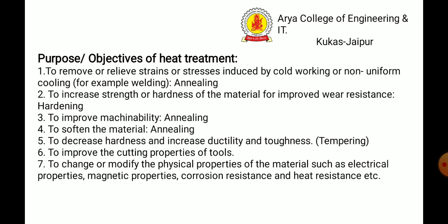The main purposes and objectives of heat treatment are, as we said earlier, to improve mechanical properties like machinability, to soften the material, to decrease hardness, to increase ductility and toughness by doing tempering, to increase strength and hardness, to improve wear resistance, and to relieve internal stresses. These are stresses which are induced during the cold working process.